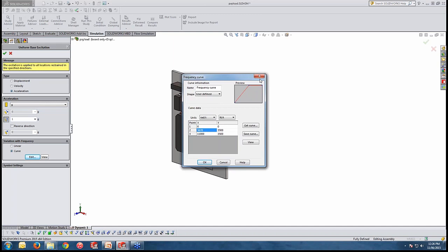So simply we put the magnitude of acceleration to be frequency dependent as the entry of our base excitation. So the unit base is multiplied by these values at different frequencies. For the range between 0 and 5670, we got that much. For the range above this, we're getting the same. All right, but the variation is like what we can see here.